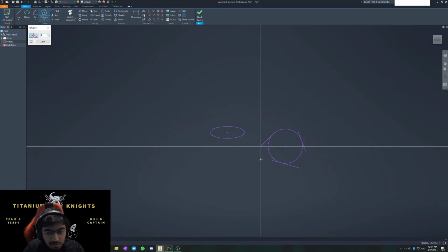And then lastly, you have a very useful tool, the Polygon tool. With this tool, you can make polygons, essentially, by either one of its vertices or the midpoint of one of its sides. And this number decides how many sides the polygon will have. So I'll put 5 here, which is a pentagon, and I'll say inscribed, and I believe this is circumscribed. Yep, that makes sense. Because when you click on a point, that'll define it as the center of that polygon.